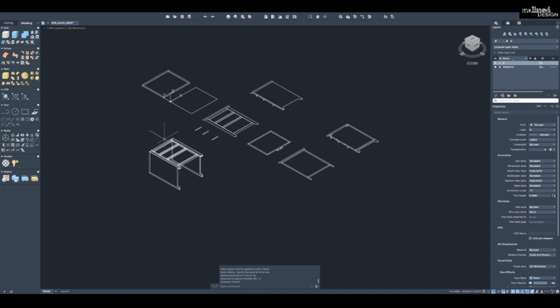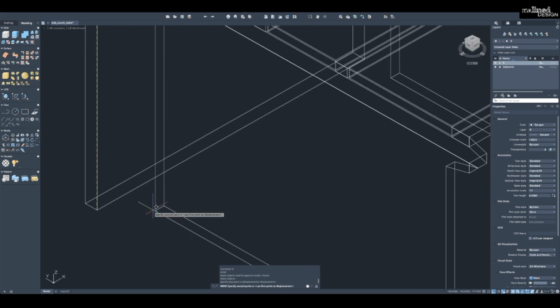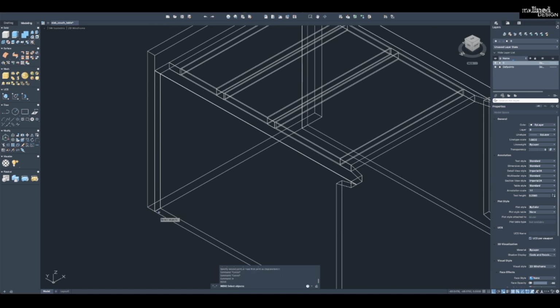Okay, so right now I could rotate this and then put the top on. So rotate, 3D rotate, grab the component, enter, and I want to rotate on the X, enter, pick a back corner, and 90 degrees, rotates the top. And then what I want to do is move from this back corner down to this corner.